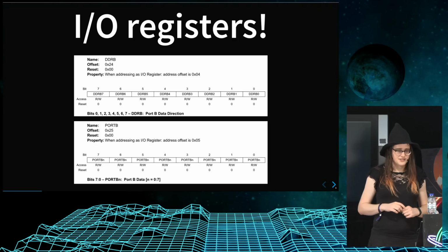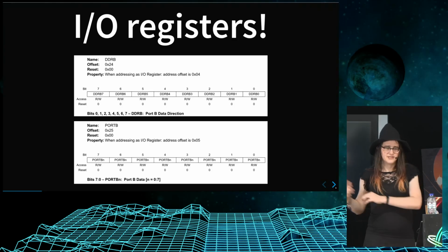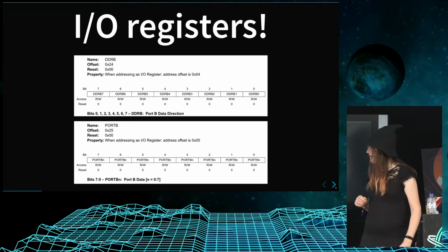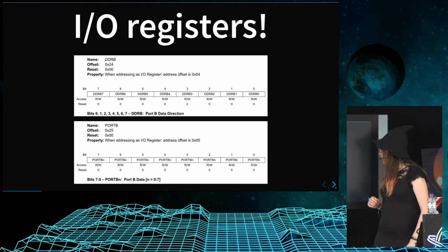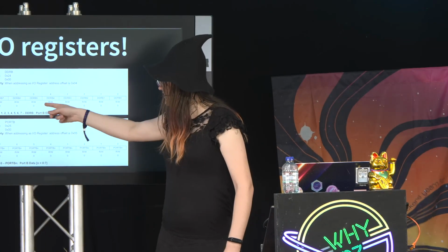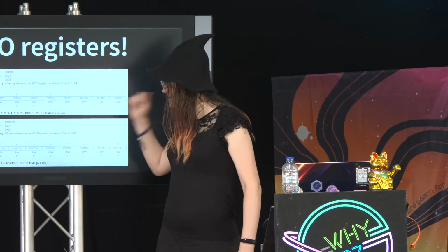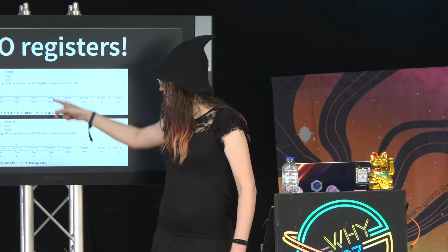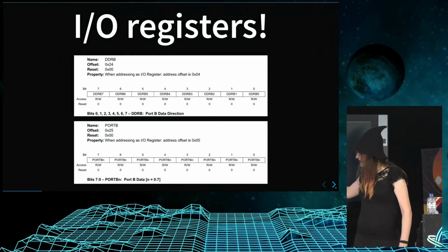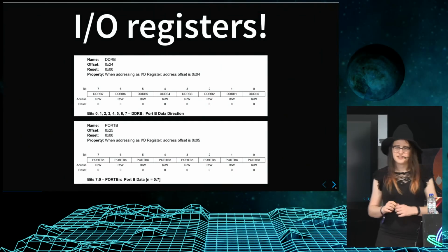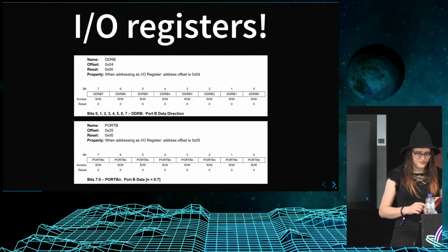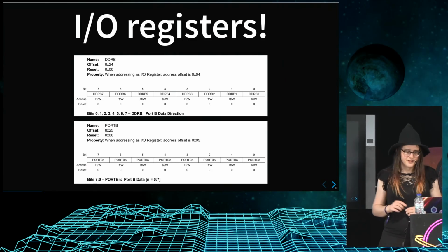Internally, that's pin B5, so port B, and then the 5th bit of port B. And here you can see 2 registers we're going to use. It's the data direction register and the port register, and you can see the 5th bit here controls this specific pin.